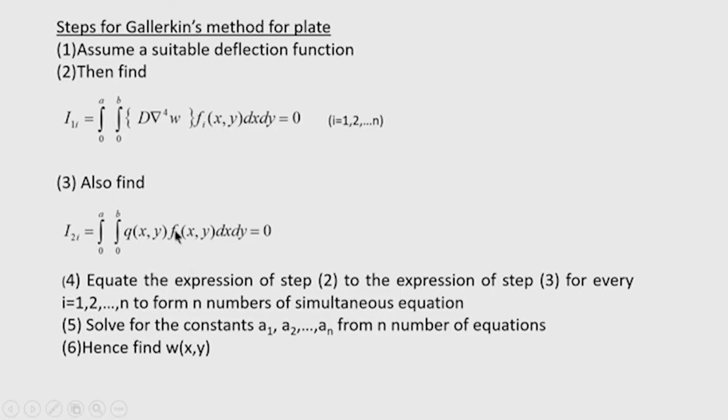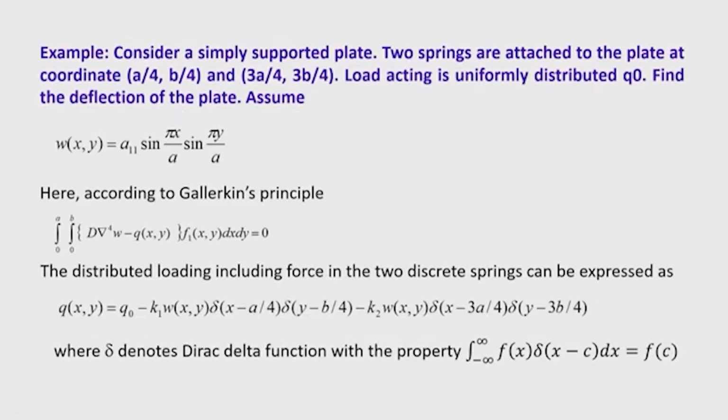Equate the expression of step 2 to the expression of step 3 for every I from 1 up to n to form n number of simultaneous equations, and these equations again will be linear equations. Solving these linear equations, we will now get the constants a 1, a 2 etc., and then the deflected surface can be composed. Okay. Let us give one example of a plate with the help of Galerkin method.